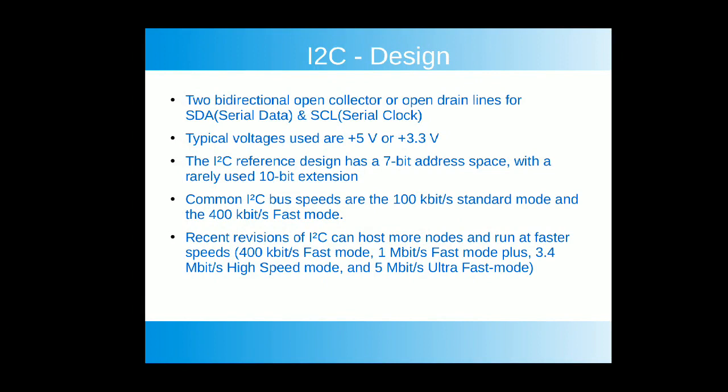Now let us see various characteristics of the I2C protocol. I2C has two bidirectional open collector or open drain lines for data communication, and these lines are represented as SDA and SCL, or serial data and serial clock. The voltage level used for the I2C protocol is either plus 5 volts or plus 3.3 volts. And we know that I2C is a multi-master, multi-slave